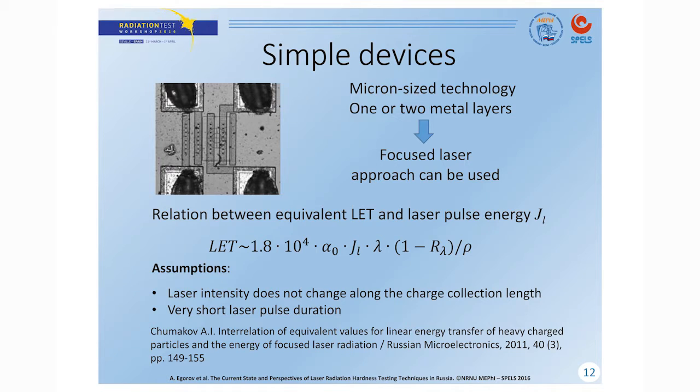For rather simple devices of micron size, like this one, the focused laser approach can be used to determine its sensitivity. When such devices are tested, it's relatively simple to determine the equivalent LET by measuring the threshold pulse energy.